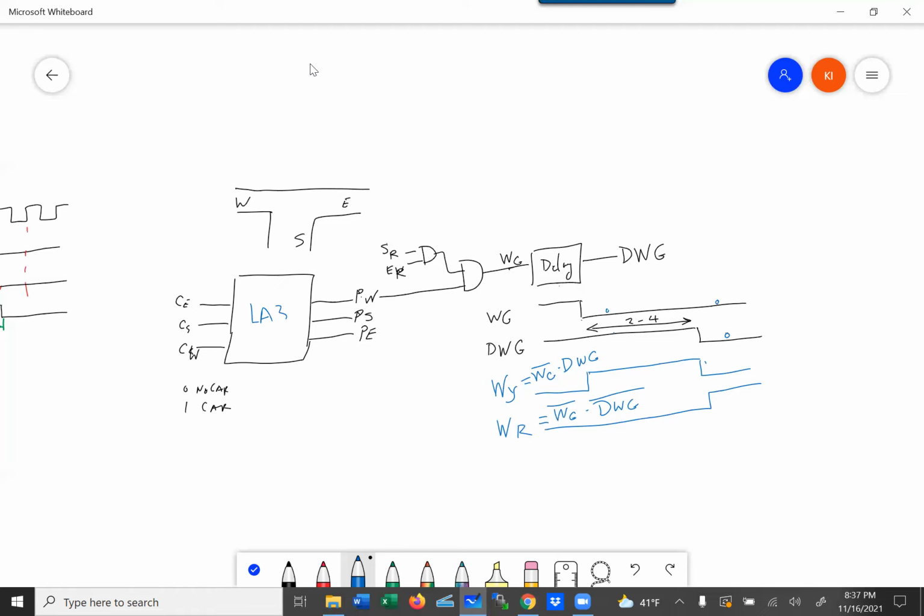Now, this process is using modularization, using what you built before. That's not to say you can't take the finite state machine design process, which we talked about in chapter 5 of Engineering 250, and do a state diagram of what you need to do, what the different 9 states are that you have to deal with, do the present state, next state table, write the excitation inputs, and draw the circuits. The only thing is, modularization is really important. You'll find that doing it bottoms up, as a design for the whole system, is just too much. It's harder than building each of the small blocks and then connecting them together, as we have talked about in the past. This is the concept of modularization, which is throughout everything we do.